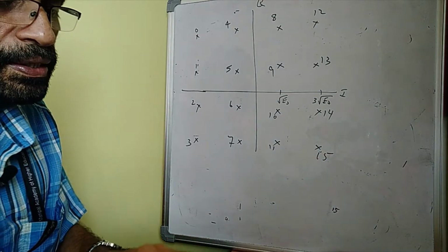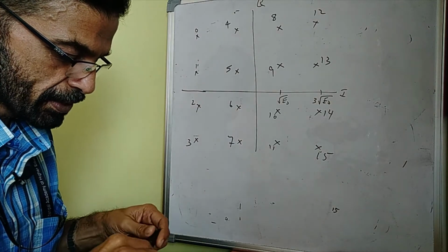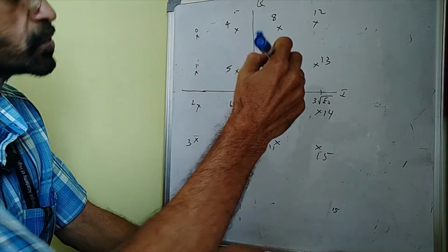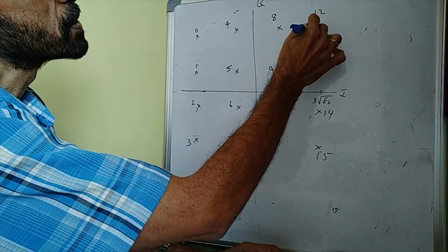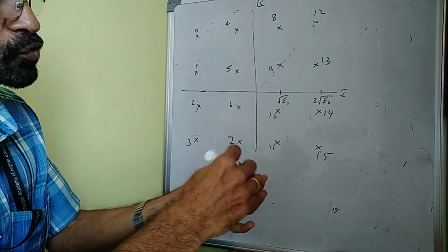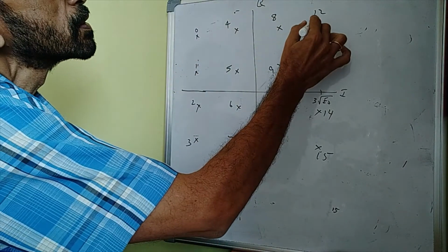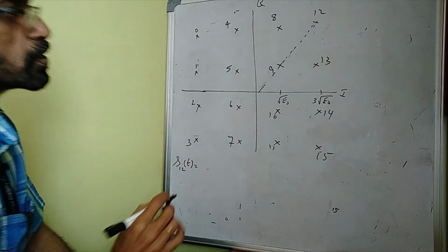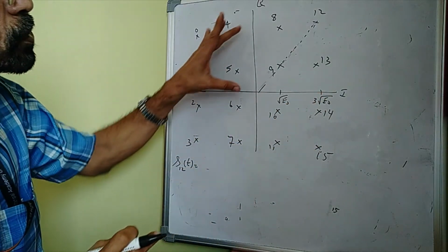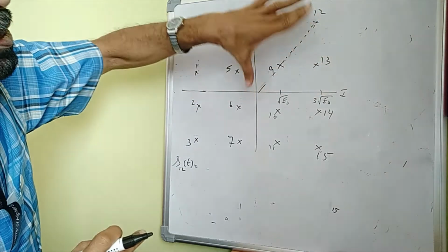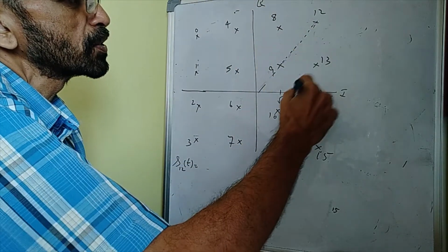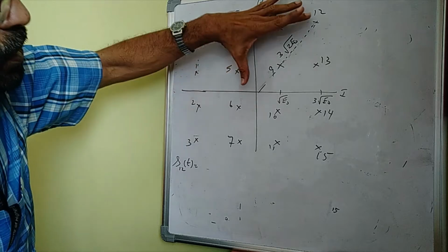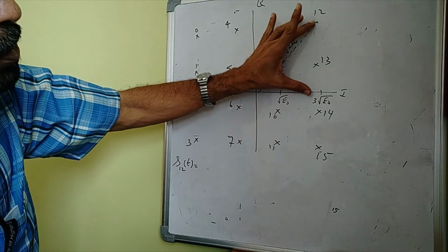Now let's say that at a particular signaling interval, signaling instant, the signal transmitted was, let's say, this. That is S12T is transmitted. Let's say S12T was transmitted. Now, S12T is equal to, now we know this is 3 root E naught. This is also 3 root E naught. So using that 1 is to 1 is to root 2, we can write this as 3 root 2 E naught. Remember, this is 3 root E naught, this is also 3 root E naught.